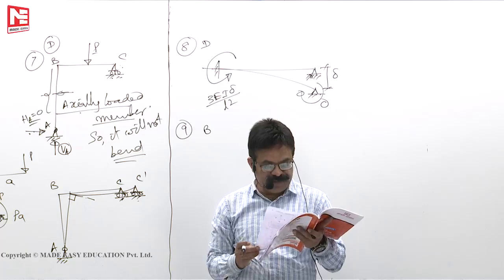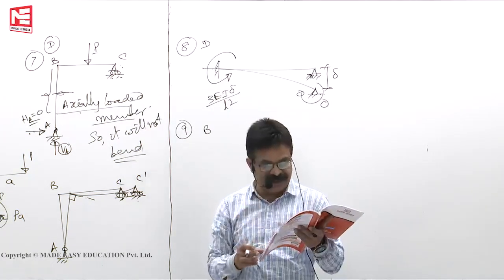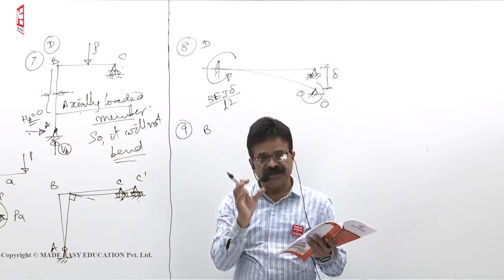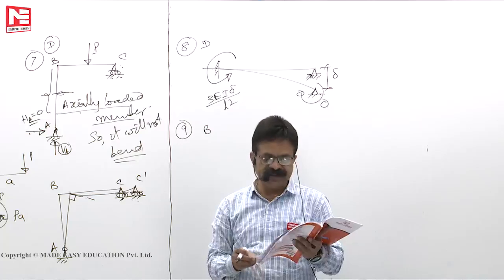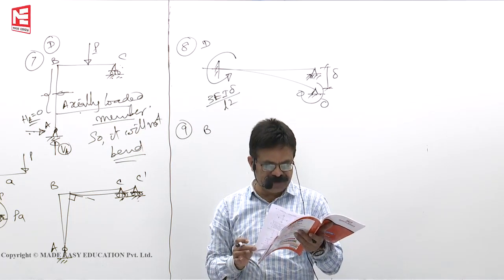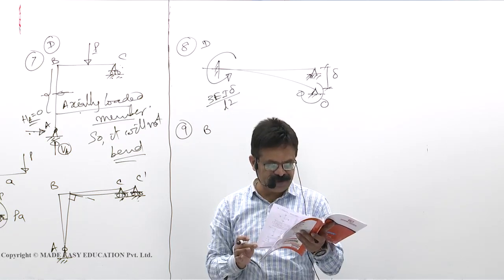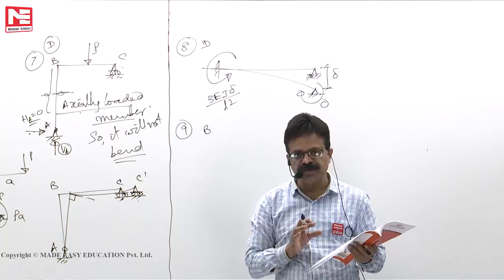Next. Principle of virtual displacements can be used to establish conditions of equilibrium. Correct. Principle of virtual displacements will give you additional equations of equilibrium. Okay. Correct method. Substitute frame method is not applicable to frames subjected to significant sway. Substitute frame method means an approximate method of the moment distribution method.